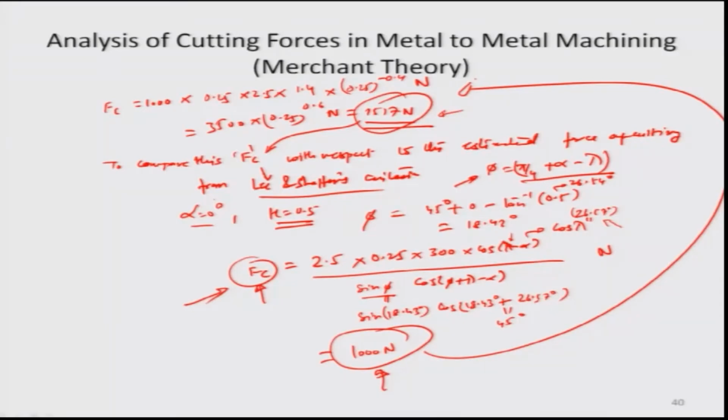Now, the other issue which I would like to take up in the next module is related to the heat transfer process and the temperature rise in the cutting zone because of the cutting action. Obviously, there is a shear plane across which the chip is being deformed, and all that energy is stored in terms of increase in temperature or heat energy, and so there is going to be a tool temperature zone which comes up because of all this energy exchange.